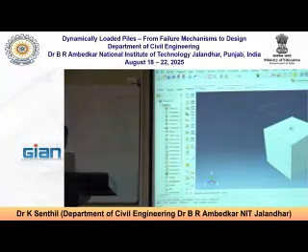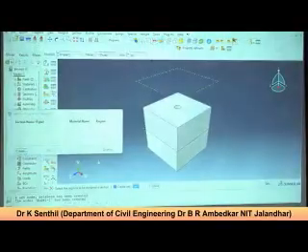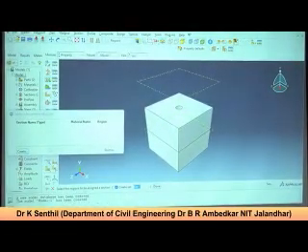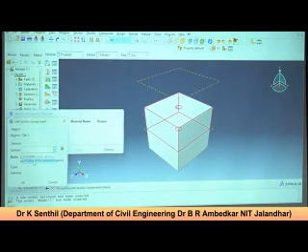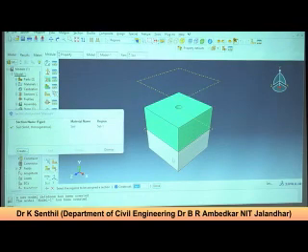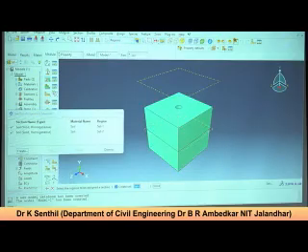Now you go to assign property, create, select the regions to be assigned. So now I have selected the top layer, create soil. Here you have to define soil 1, soil 2, or sandy soil, clay soil, whatever you like. Now it's done. Now the bottom layer you do the same, soil. So both the layers are now modeled.